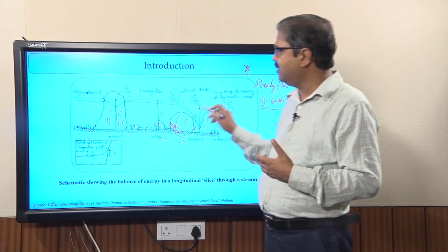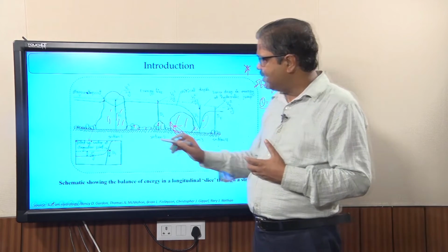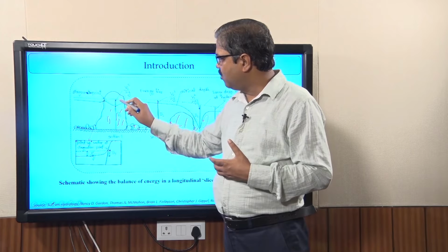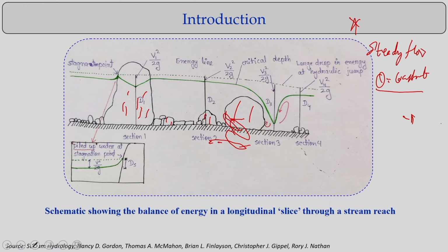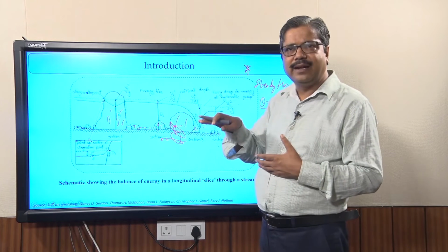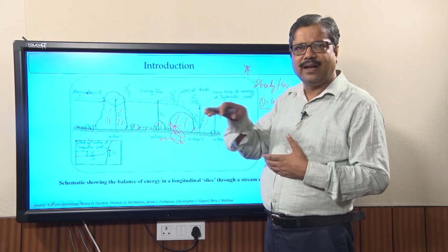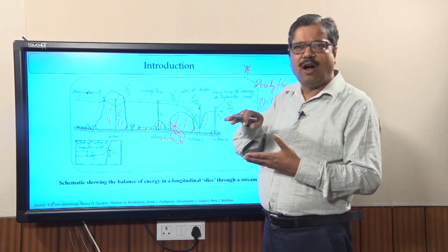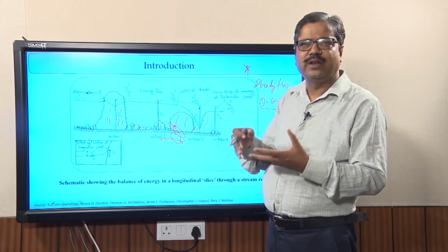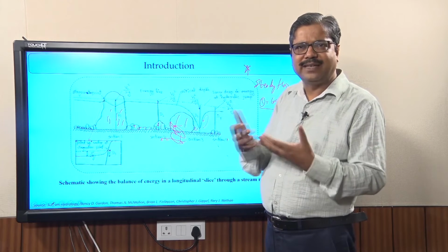If you look, there are the hydraulic gradient line and the energy gradient line, and as the flow passes these boulders, the V1 velocity flow happens again; the stagnation point is here. After that the flow again happens with velocity V1 increasing, and because of the presence of these boulders there are certain energy losses happening. That is reflected in the slope of the energy gradient line. The slopes indicate how much energy loss happens because of the boulders, which we can quantify using Manning's equation.